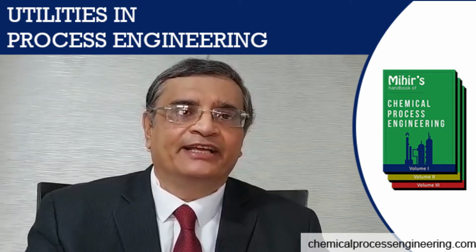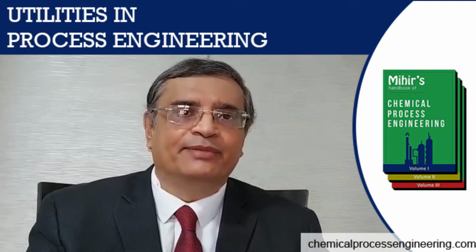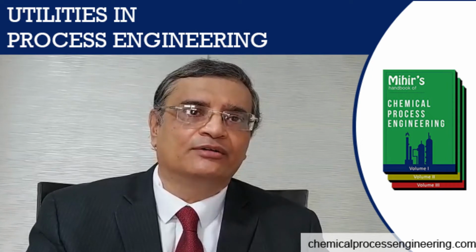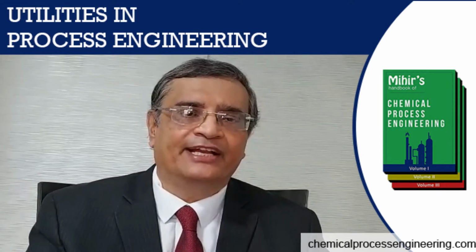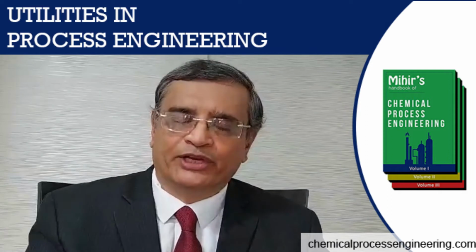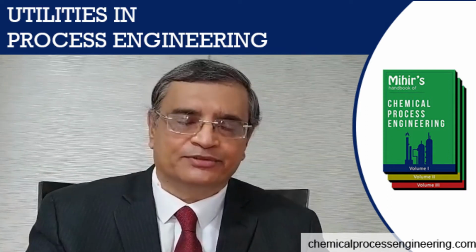Now a utility, as all of you are aware, is a medium which is either directly used in the process or which is indirectly used and is reusable. For example, you have steam stripping, which is a direct usage of a utility in a column. Alternatively, you have cooling water systems, chilled water systems, which are reusable systems.